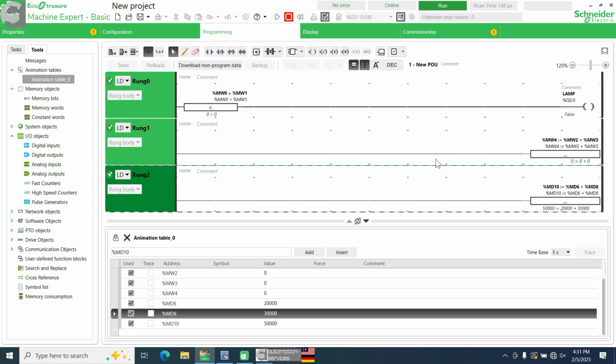So analog input for me is any device that can measure and give me a range, a value. Analog output means, if you see analog output, mostly any device is motorized, like controlling a motor speed. Analog output can control a motor. Analog output can control a pump, still a motor. Analog output can control a valve, open and close, still like a motor. Analog output can also control a damper, still something like rotation. So analog output is mostly to control a rotation.